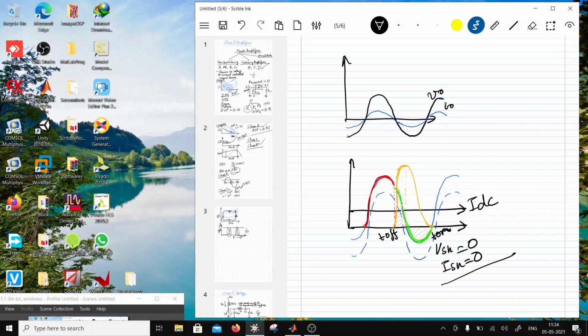Okay, so now using this, what's happening is this waveform, if you do its Fourier expansion, you will see the fundamental is there, and then the third harmonic is 17 dB down, and then the fifth harmonic is way down. Second harmonic is 17.